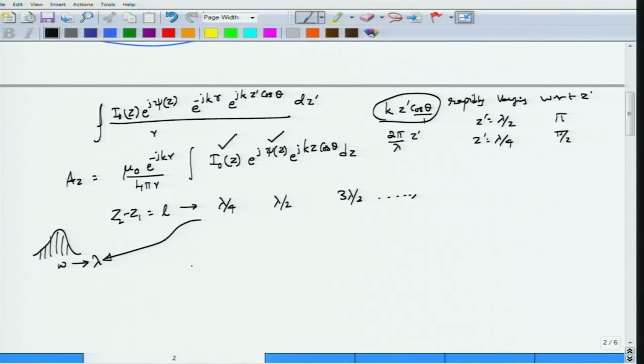Well, imagine that before this became an antenna, it lived as a transmission line. These two pair of wires were a transmission line, and then I had a source connecting and exciting this transmission line. At the far end, there is no connection, there is no load, which means that this is going to be an open circuit. If you were to draw the current pattern, you would see that the current has to go to 0, and then the current would essentially be uniform over here.